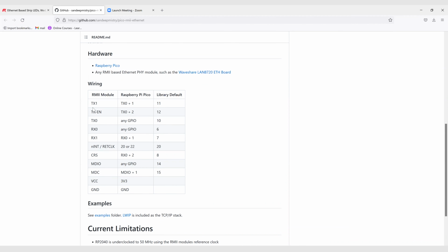But anyway, there should be another column here with pin. That would be cool. If you see here TX1, it's got to be on any pin that's TX0 plus 1, because TX0 and TX1 are 2 data bits that have to be together. TX0 can be on any GPIO, but the next pin, it actually rolls over.